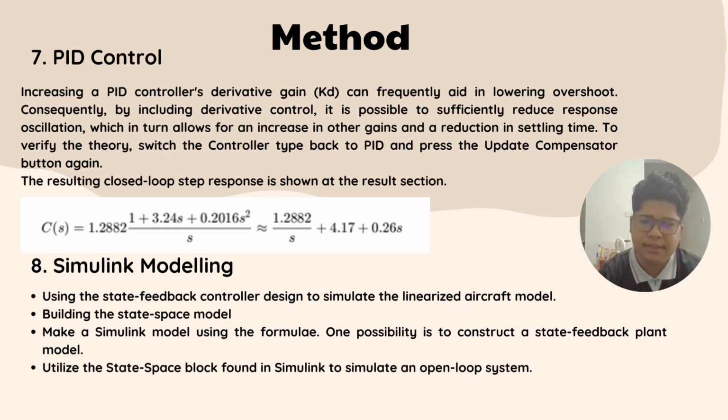And next is the simulating modeling method, which is using the state feedback controller designed to simulate the linearized aircraft model and building the state space model, making a simulation model using the formula. Another possibility is to construct a state feedback plant model. Utilize the state space block found in Simulink to simulate an open loop system.